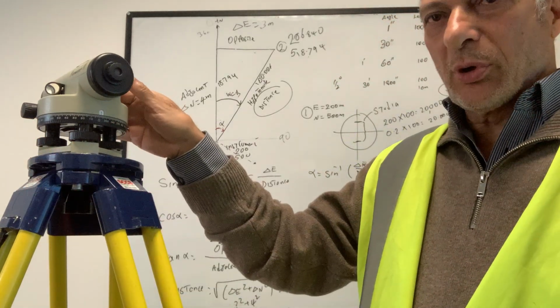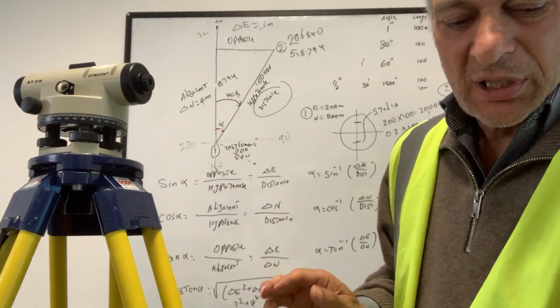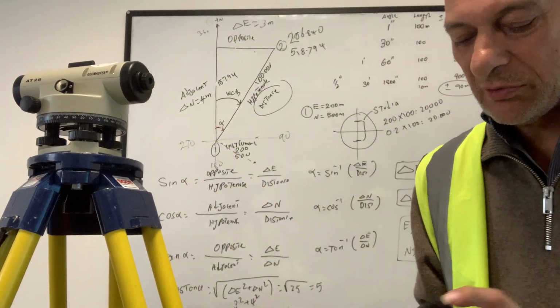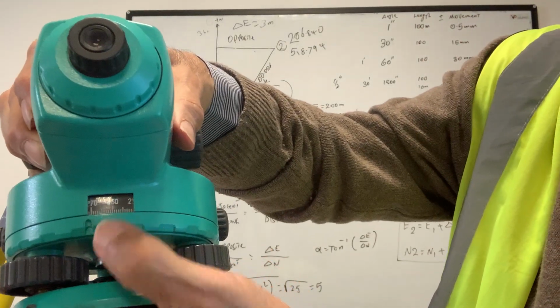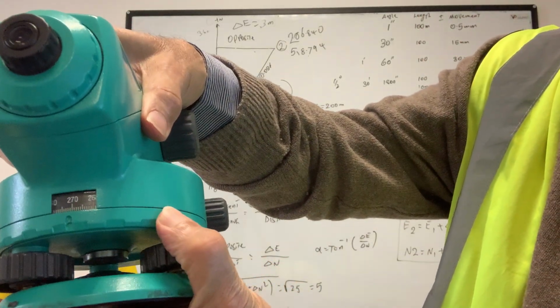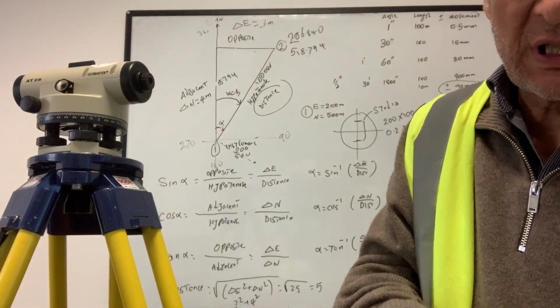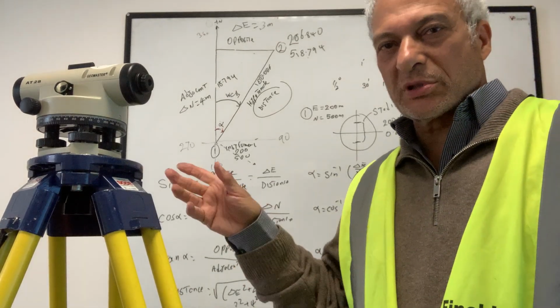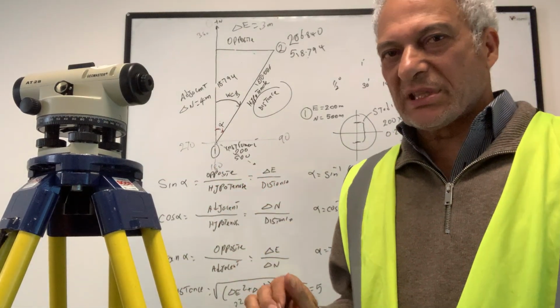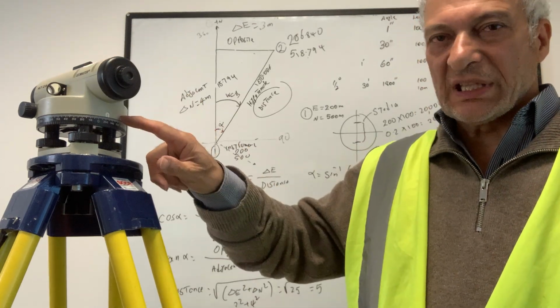And then as you point and turn, you can read the angle on the screen. I can show you with this one, with the other one here, that you've got these angles in here, and you can turn this base and rotate the angles until you get 0 degrees. And once the 0 is pointing towards where you're sighting, the instrument is set for the angle. Then as you turn, you read the angle.